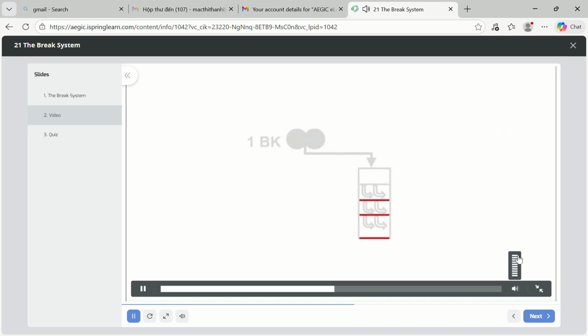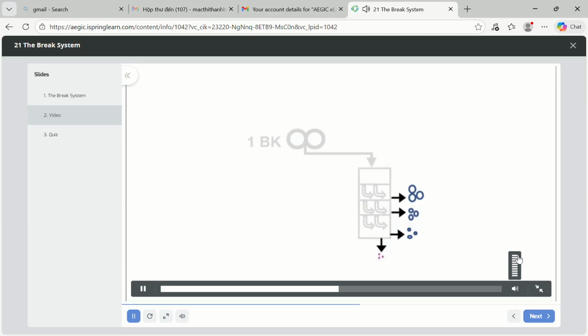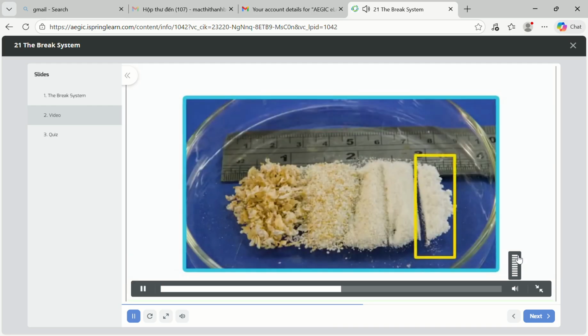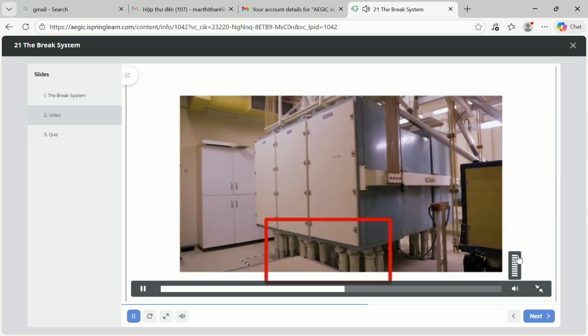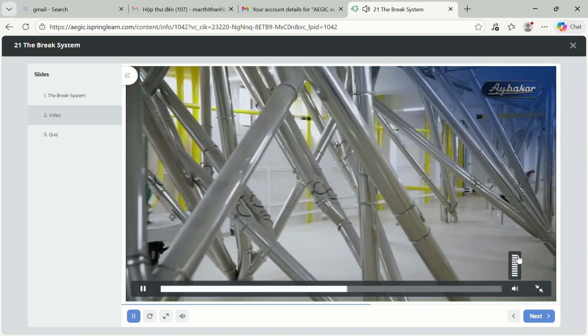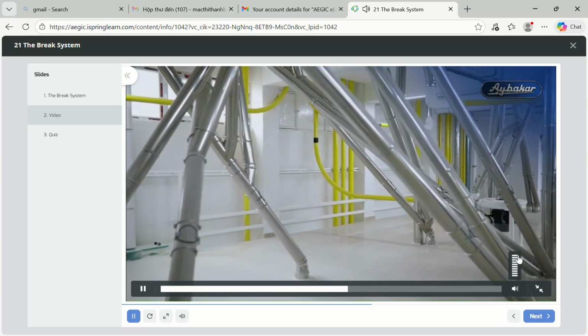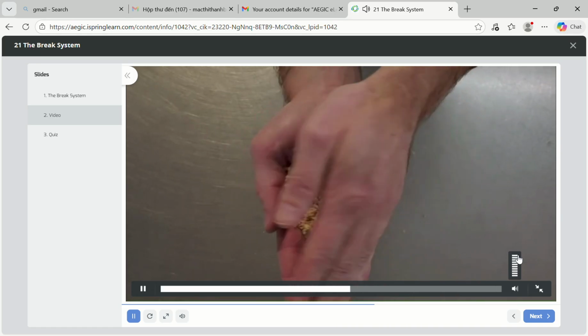The remaining material continues to travel over progressively finer screens, separating the stocks into different size classes. This is called grading. The finest screens are flour covers, and the stock passing through these is flour. Flour sifted out in the various plan sifter sections is removed from the milling system as soon as it is sifted out, via spouting to a flour collection conveyor. This is to prevent the flour from becoming contaminated with bran from the milling processes.